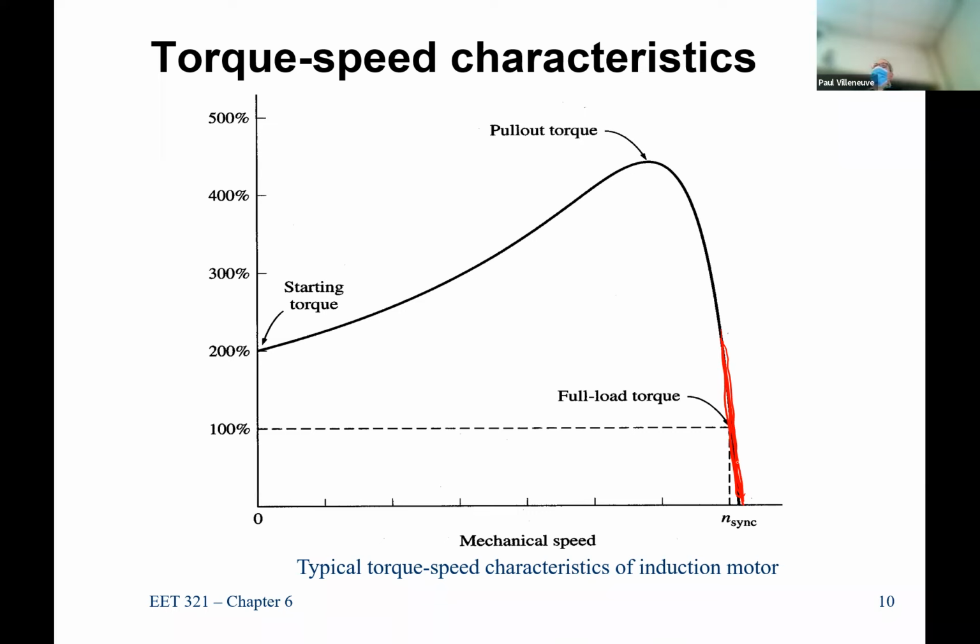So if you're trying to figure out speed of operation, if you add more load or remove load, you can predict pretty well, without having to spend too much time, what that speed will be, because you can do y equals mx plus b. You can find the slope of the line and you can figure out for a 2 RPM speed change, you can get an approximate change in the torque.